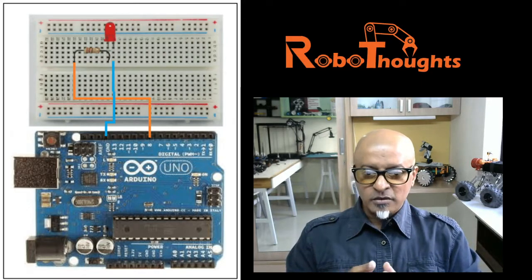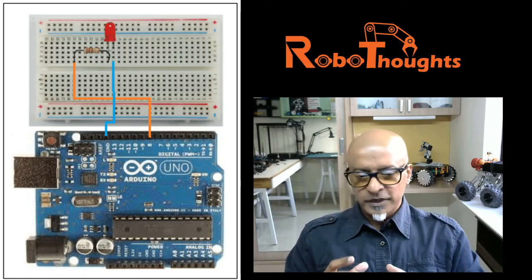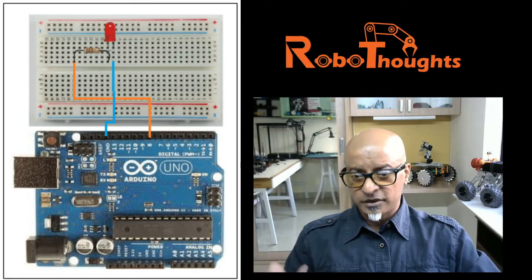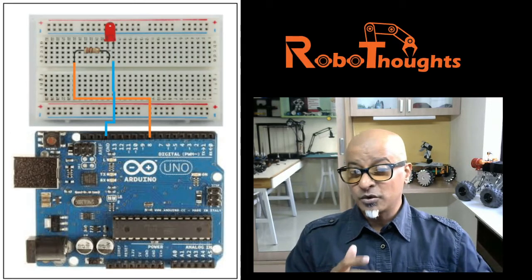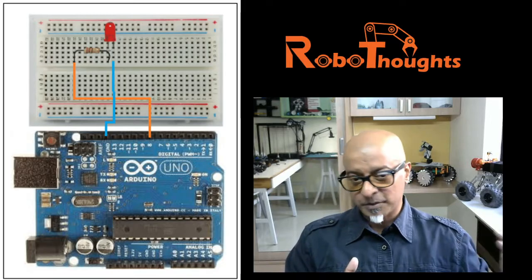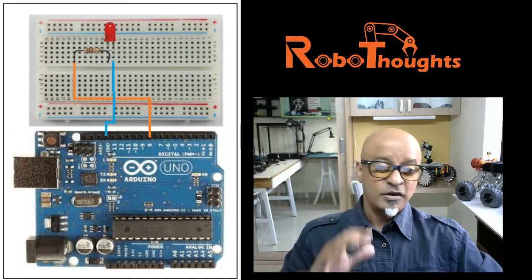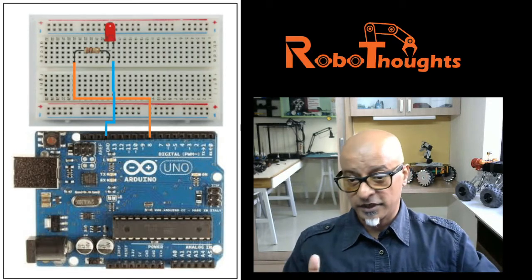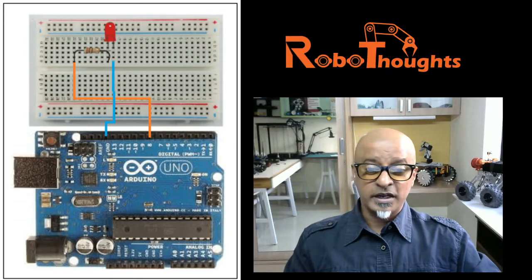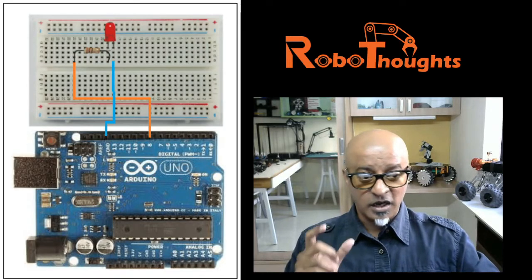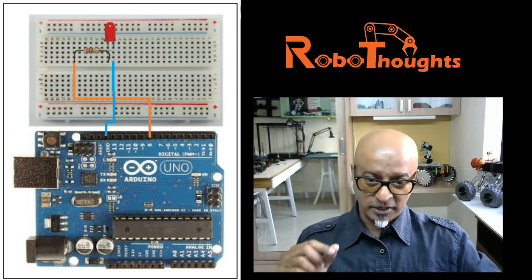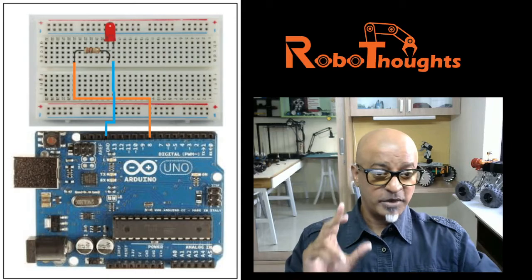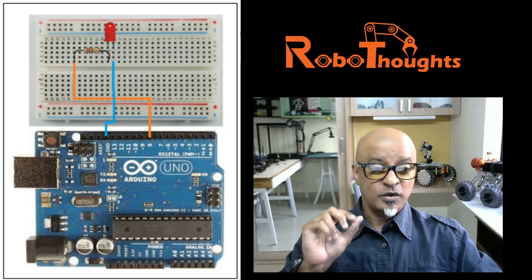In Arduino UNO, you have certain limitations in terms of the number of digital pins and analog pins. So we can use 8, 13, 7, 4 and 3, and the other pins are PWM. I am going to talk about PWM in detail in an upcoming lesson, which is a different topic altogether. For now, you can just say digital pin 8, 13, 7, 4 and 3. One terminal of the LED is connected to the ground, while the other terminal is connected to the digital pin, and the pin has only two values. Make a note of it. The digital pin has only two values.